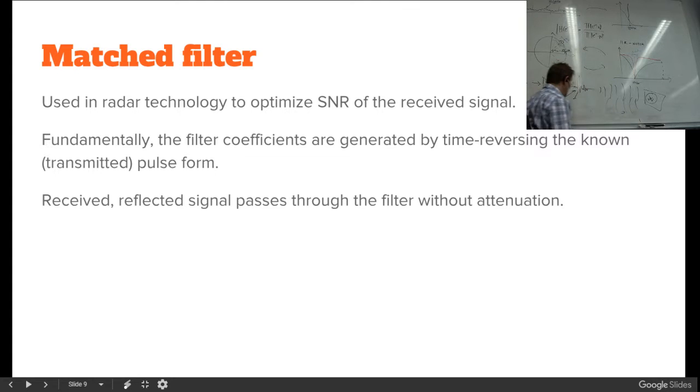That's actually a digital domain filter. You make a perfect filter which is just the reversed data, and that works as a filter to your return. That is called a matched filter, since it recognizes only pulses of this shape that are returning back. Matched filter. Okay.